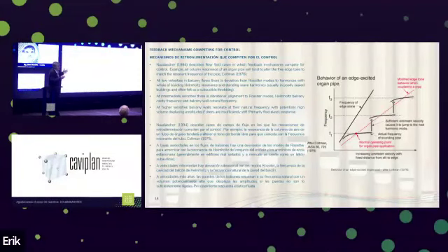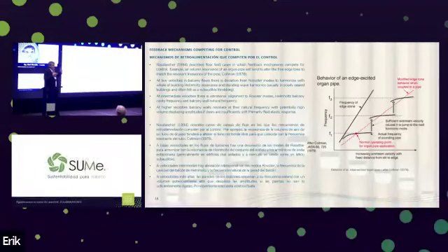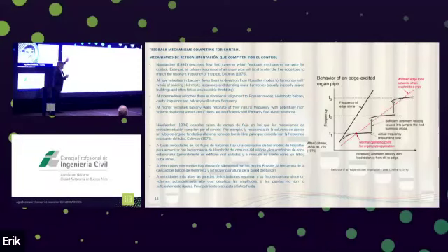As the wind speed increases further, we start to actually align more with the stiffness of the walls themselves. And we have a transition, particularly in the serviceability range, from an acoustic loading through to a true wind loading mechanism as we increase in wind speed.